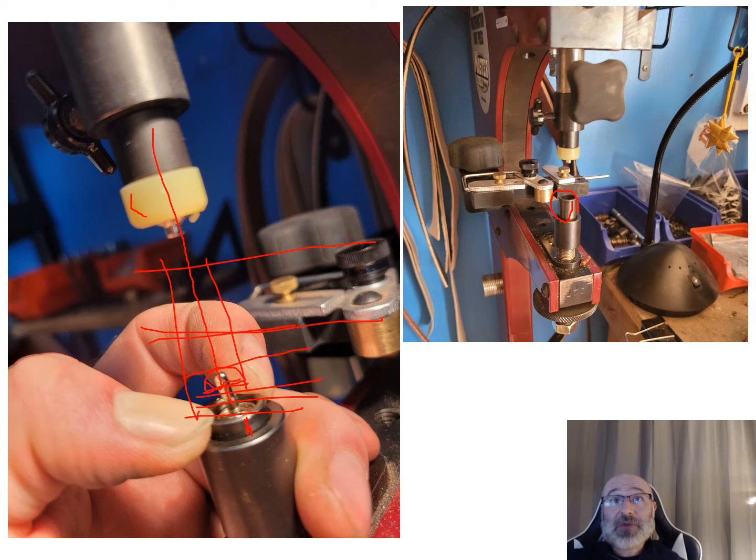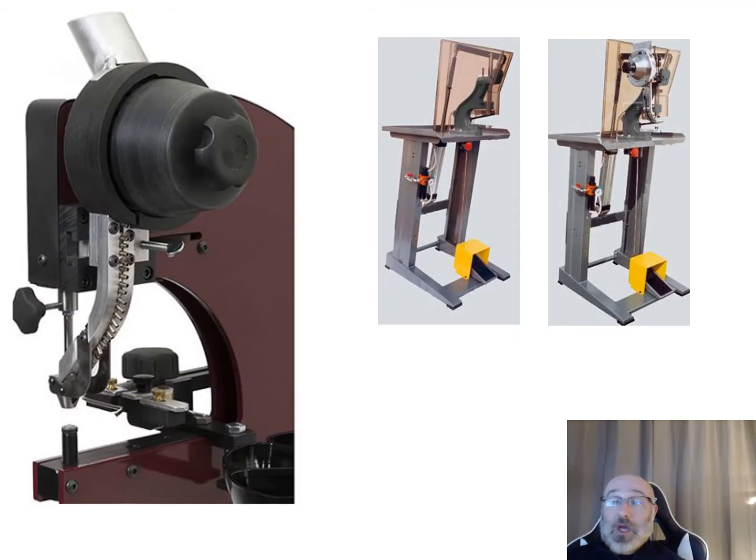I can utilize both hands, but I still need to manually put the head and the stem of the rivet into spot for these double or rapid rivets. So the next step we can do with automating these is we can put in an automatic rivet feeder. So you get a big hopper up top here, and it has a sorter inside this that automatically aligns these rivets. You can see these are all going to fit in just perfectly, feed down from the top here, and then you have your set down here at the bottom, whether you're using rapid rivets or tubular rivets or tubular rivets with a washer. There's different types of adapters you can get for this right here, and this is that same multi-function machine that I showed on the previous slide there.